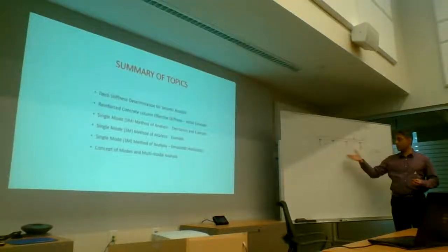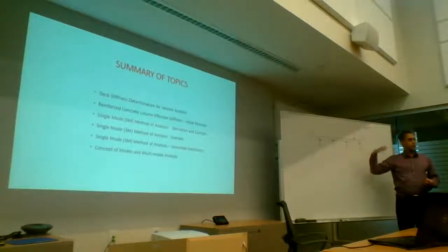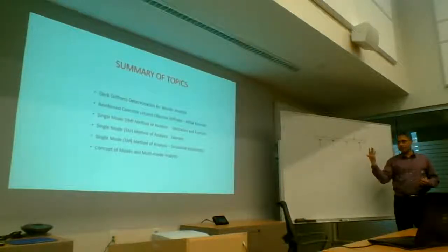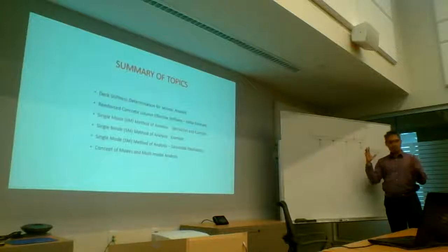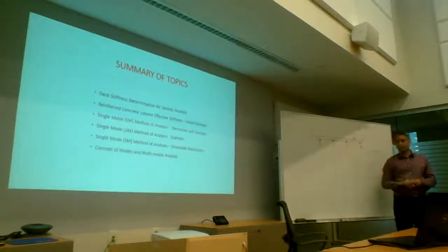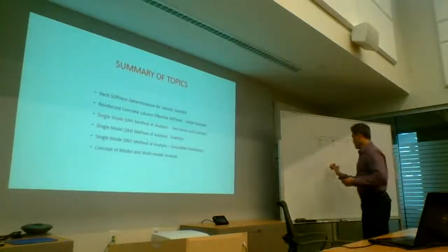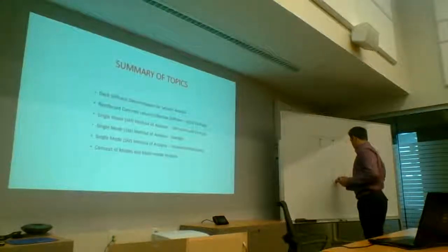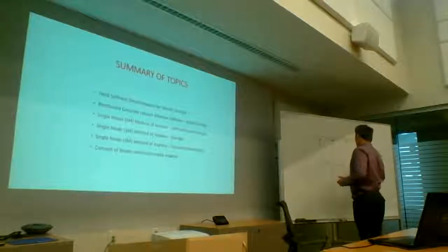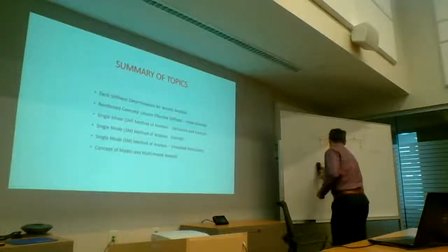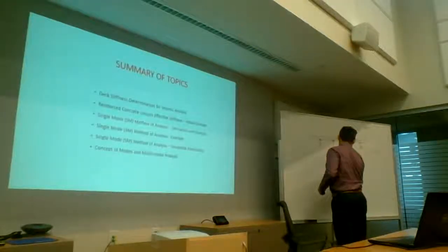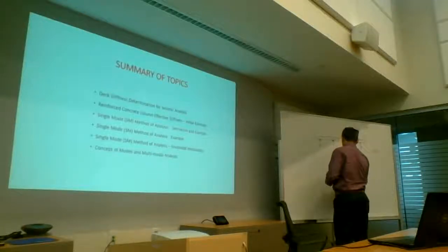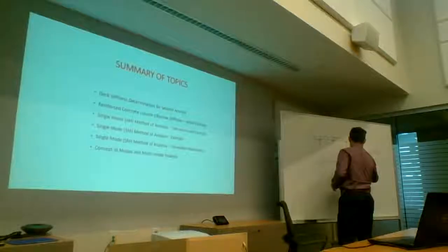There is just need to capture the overall mass, the overall vertical and transverse stiffnesses, and the appropriate area for this. And if your bridge is, say, multiple spans, say 2 spans, just to keep it simple, you can model the deck with a stick.